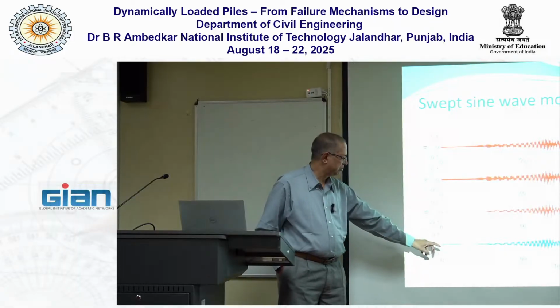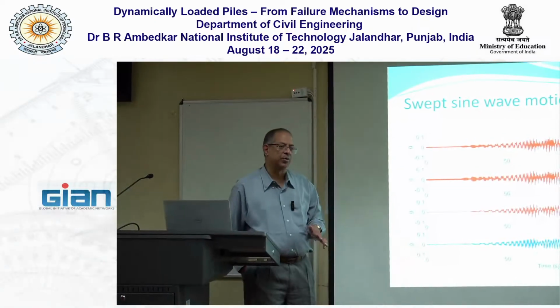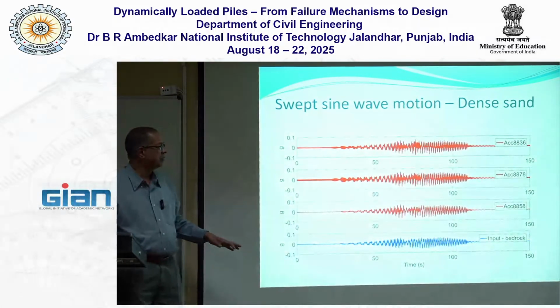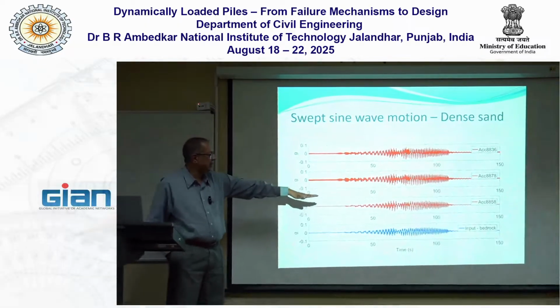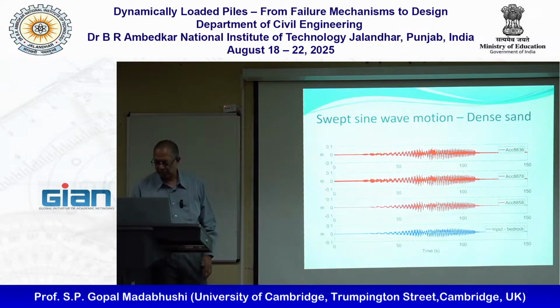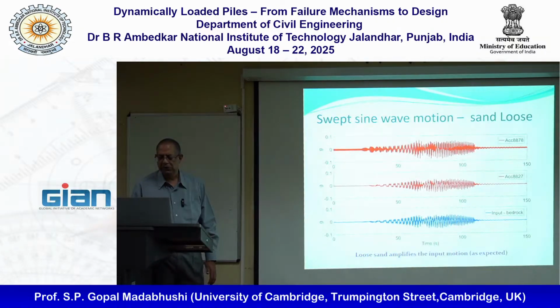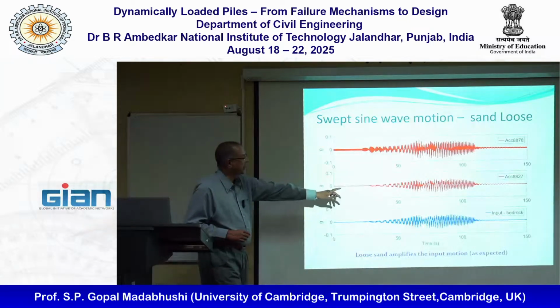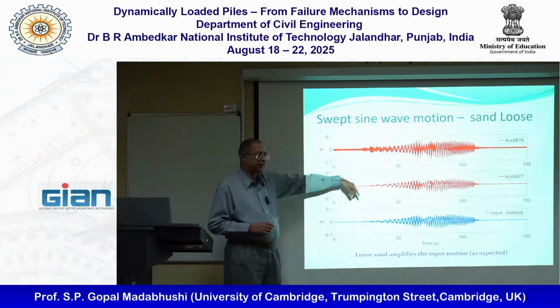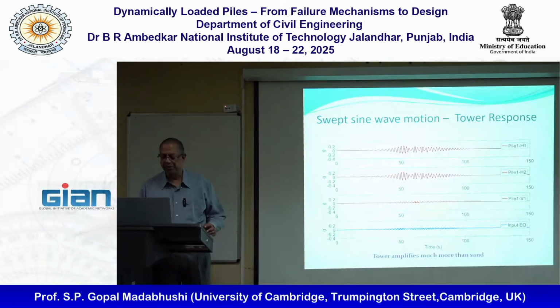Small is less than 0.05 g. So it's not going to destroy the model or liquefy it or anything. And then you can see the acceleration at different points in the model. You can see in the loose sand, it amplifies a lot more, the same input motion.